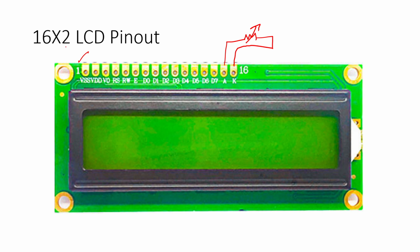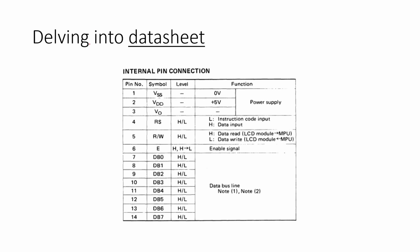the LCD varies. And this VSS you can connect to ground, and this VDD you can give 5 volts. Coming to RS, RW and E: RS is known as register select. What register select and enable are, we'll see in the further part of this video. From D0 to D7, these are the data lines on which you can keep your data or command based on your requirement. Coming to the description of each pin, VSS will be connected to 0 volts, VDD will be connected to 5 volts, and VO you can just leave.